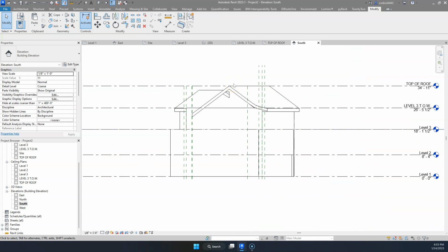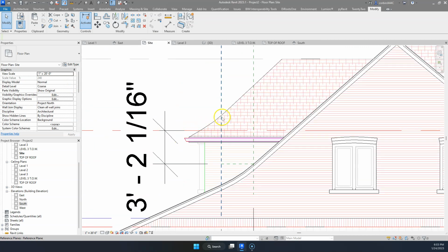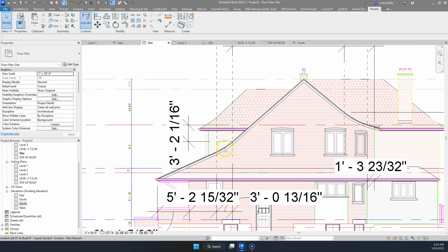I don't know. I think depending on how much detail you want to get, maybe ignore these slopes for now. Just like straight. Yeah, and just do these ones because these ones are simple slopes, whereas these are complex because they meet in the corner as a hip. So just do those slopes for now, and then what you might want to do is model it as a mass, whole roof, just because it's so complex. But start with the roofs by footprint, or you can model just the edges as a mass.